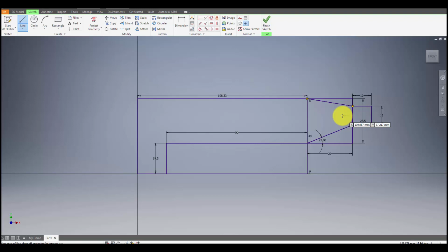Next it says draw a 31mm by 25mm rectangle from the top of the 12mm rectangle plus 9.5mm for position. So what that means is if we select the rectangle tool, we bring the cursor so it's directly above and it gives you that little telltale there. I'm simply going to click and drag. I've chosen the wrong line there, so press escape, choose the rectangle tool. It's this side here that's got to be level with. You can see how it indicates that it's exactly level there.